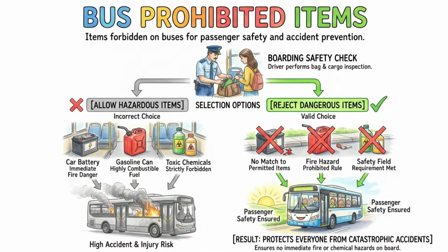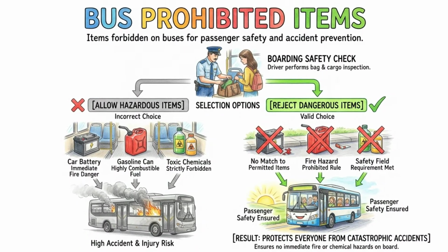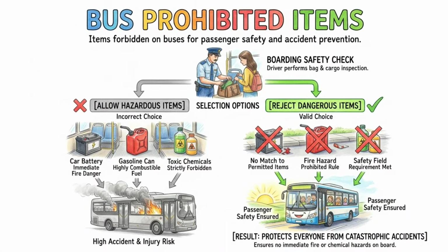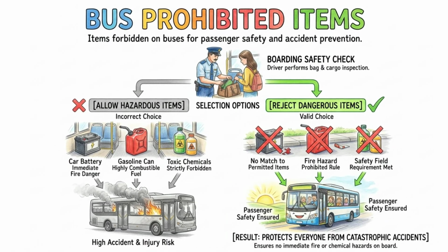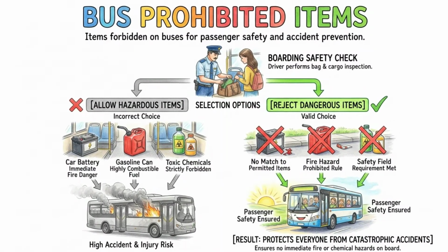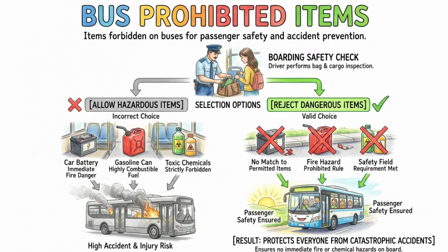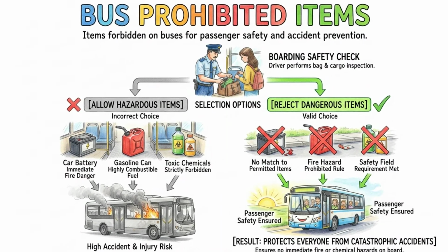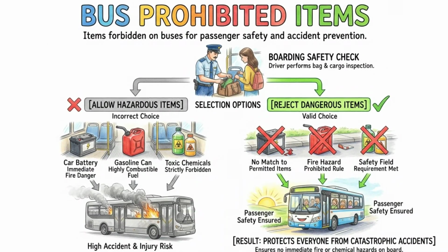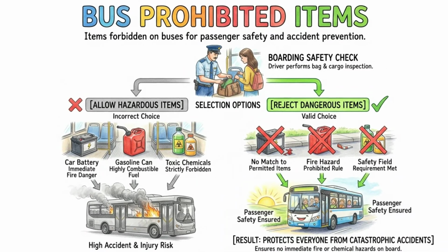Once your load is balanced, you must secure it properly using tie-downs to prevent it from flying off your trailer. The golden rule for tie-downs that you must memorize for the exam is that you need at least one tie-down for every 10 feet of cargo length, or fraction thereof. However, no matter how small or light the cargo is, you are legally required to use a minimum of 2 tie-downs. This ensures that if one tie-down snaps or comes loose, the second one will keep the cargo safely on the trailer and off the highway.